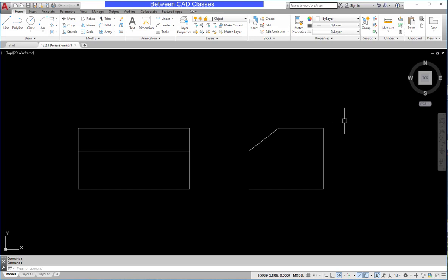In this lesson, we're going to take a look at how we can add linear dimensions in AutoCAD. Before placing a dimension, I want to make sure I have the dimension layer current. This is so that I have some different clarity on screen, but also because dimension lines should print thinner than object lines. A linear dimension is one that is horizontal or vertical, regardless of the points being selected.